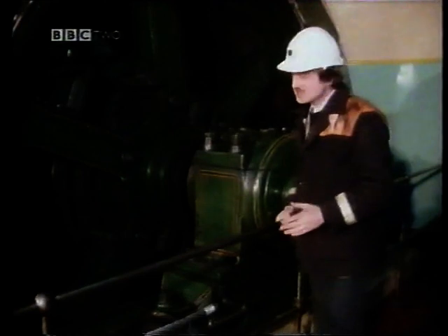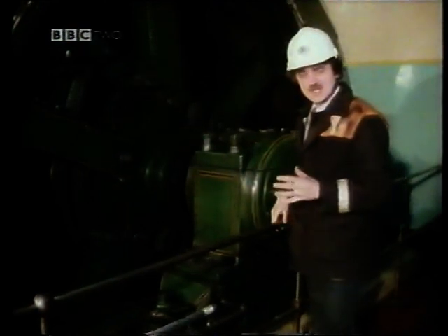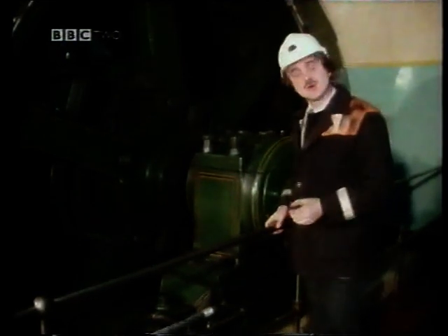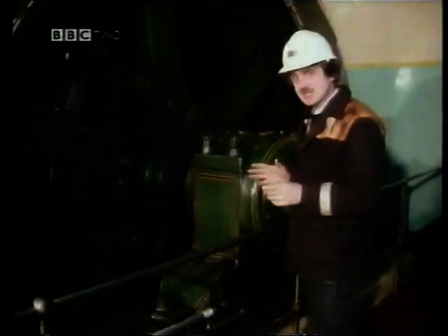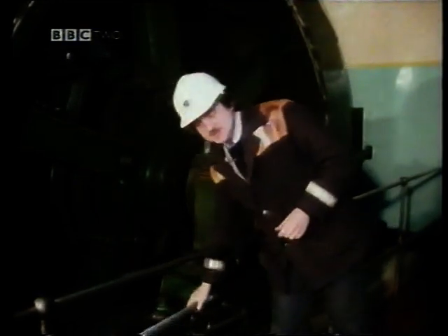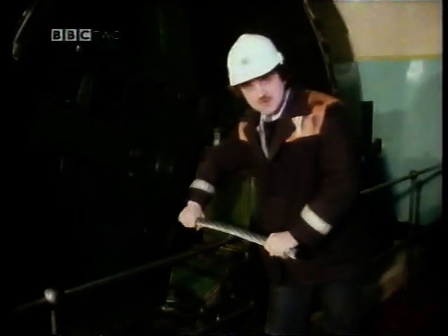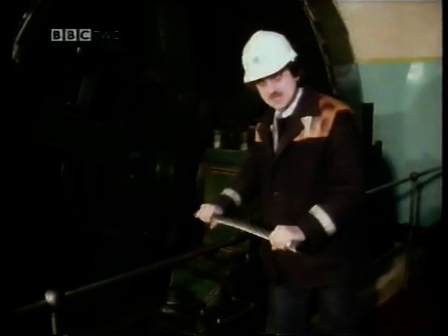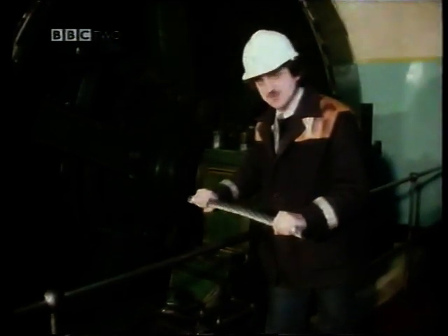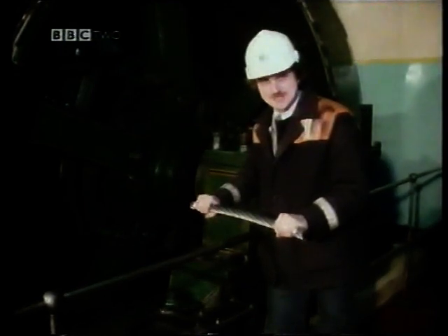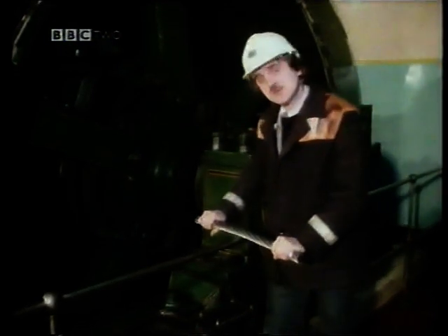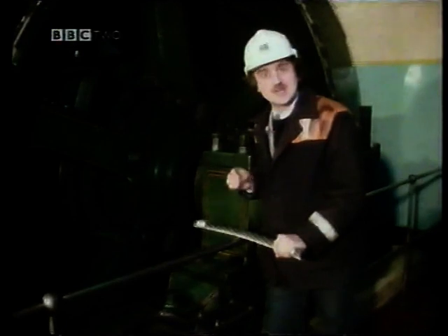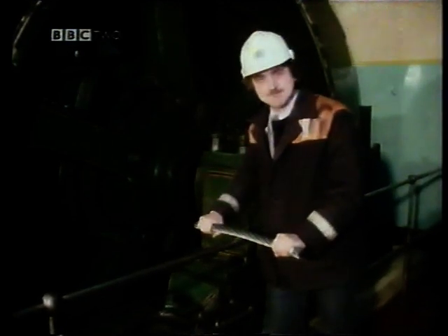Well, in the winding house, this huge drum acts like a simple winch to hoist the rope. But what determines the size of the drum? Well, for a start, it has to be of a large enough diameter so that the rope doesn't suffer too much bending as it's wrapped around the drum. And the theory of bending gives us a way of calculating what the maximum curvature is that the rope can take before it reaches its strength limits. And in mining practice, they use a ratio of drum diameter to rope diameter of 120 to 1, which is well above the safe condition by a factor of safety of 10.